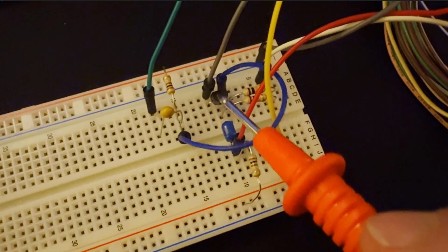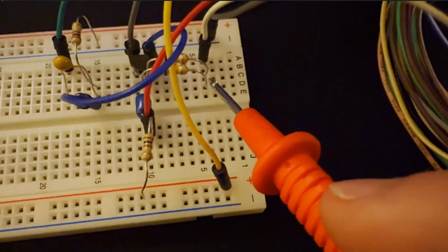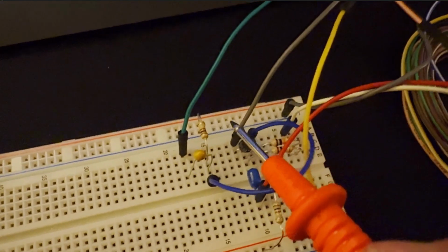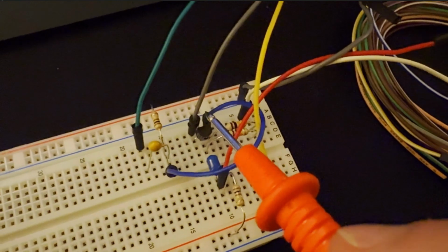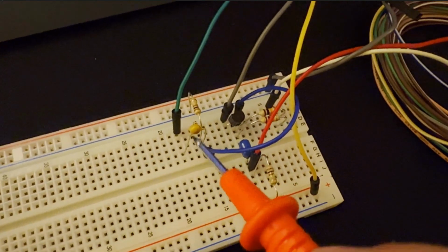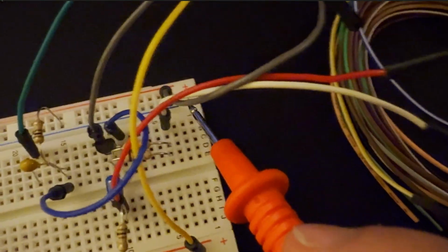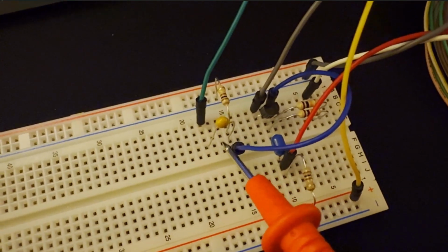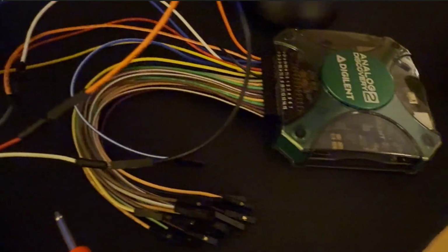Then that capacitor is connected to the base of our transistor, where from the base we also have those two 10Ks in parallel, where at the end here, those two 10Ks are wired directly to AD2 ground. Now the collector of the transistor is directly wired to positive 5 VCC of the AD2. And looking from the emitter, we go into our load resistor, which is connected to, in this case, the negative 5 volts, which is also from the AD2. Then from this junction, through this capacitor, we measure the output voltage on channel 2, also on the AD2.